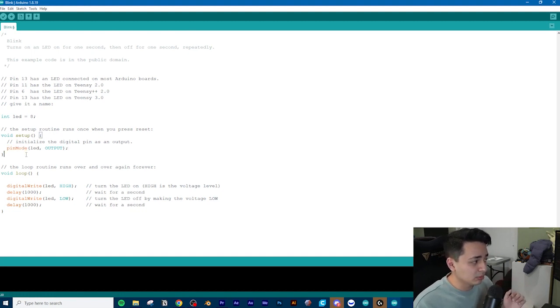So we have to communicate that information to the Arduino, and that's all that's happening here. So pinMode establishes this line of code, and then you do an open parenthesis, and usually these types of functions take a certain amount of arguments or parameters that are separated by commas. So pinMode specifically here is taking 2 arguments or parameters. The first one is basically what port you're talking to.